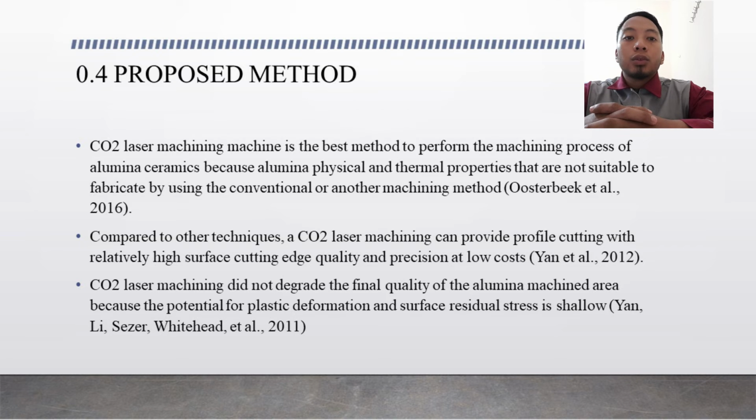Second, compared to other techniques, CO2 laser machining can provide profile cutting with relatively high surface cutting edge quality and precision at low cost, by Yan 2012. And last, CO2 laser machining does not degrade the final quality of the alumina machining area because the potential for plastic deformation and surface residual stress is shallow, by Yan Lee 2011.